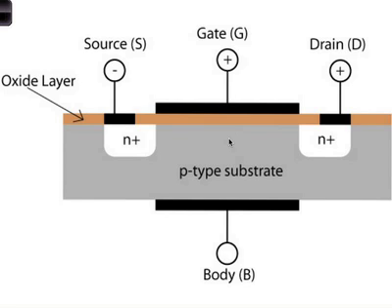Now, that capacitance is important because when you do amplification, the signal goes on the gate. Right? So the RC time constant when you apply an AC signal there is set by the capacitance here, not here. That's the input capacitance. So we need to know that, and we need to understand how it varies. That's what we'll focus on today. The current-voltage characteristics are a little bit different. It will be in this direction, just like the FET. That's what we saw before, very similar to that.